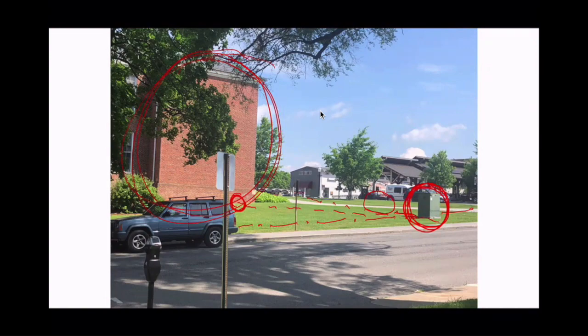And those cabinets, by code, need 3 feet clear in front of them and 6 feet clear in height. So in other words, the fireman, when everything's dark and smoky, has to be able to get to the switchgear without having to move a bunch of things out of the way, or without having to squeeze in a really tight space with his oxygen and all of his equipment.